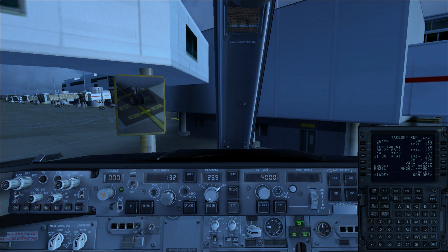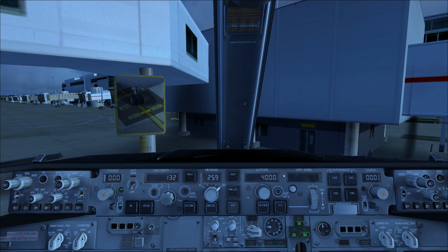Flight director on the side who's commanding the aircraft first. So if captain has control, you switch the captain's flight director on first, and then the first officer. If it's vice versa, then you would switch that off and switch it back on. So master goes to the flight director of the first officer. And again, if you want to reclaim control and you're the captain, then switch the flight director of the first officer side off, and then you will relinquish control.